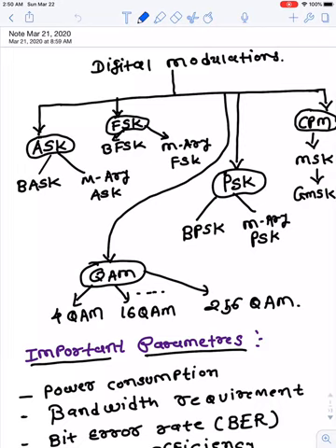In the first lecture, we have learned about the necessity of digital modulation scheme. So we have discussed over there the baseband signal is binary in form, which is of low frequency signal, and if we are transmitting directly that signal without the modulation, then at the receiver side we need a larger antenna to receive the signal, and in some cases the size of receiver antenna is in kilometer that we cannot afford.